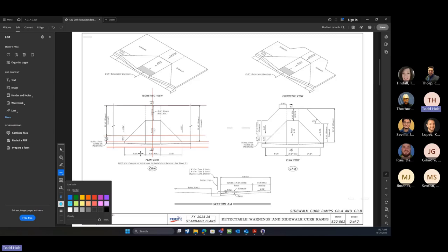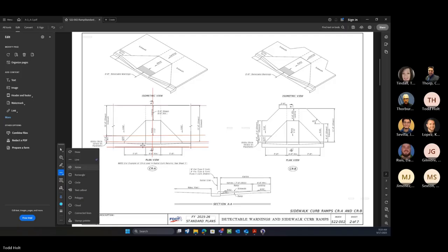Right. So what controls would we need? I like to build into my civil cells little handles that are easy to see. They're on a construction level that you can turn off and on. So maybe off of the edge of pavement line, or maybe it's that curb back top. Thinking about what's controlling that civil cell, I might build a handle that I can use from center line. So I'm going to rule that.